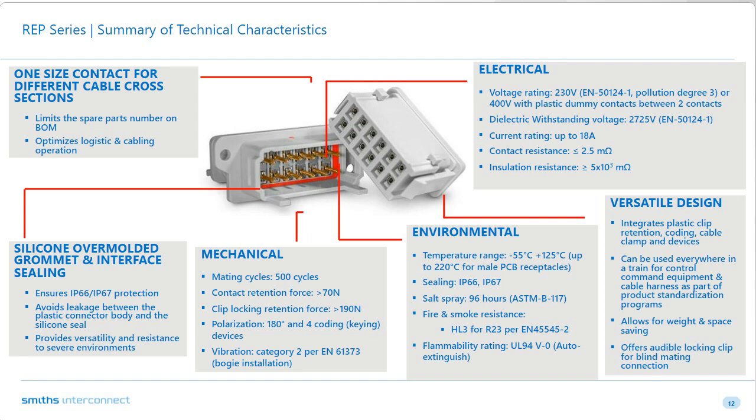Now, you might wonder why is it, right? Because as I said, in some instances, we have seen that the temperature fluctuation can be quite sharp, if you like, and hence we have to make sure that it has got a very wide temperature range to that end. I talked about the sealing, so not laboring on that point. It's got a salt spray test of up to 96 hours, and it meets and complies with the fire and smoke requirements and the flammability requirements.